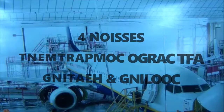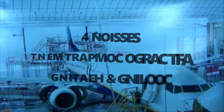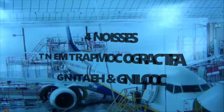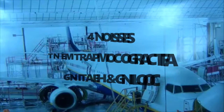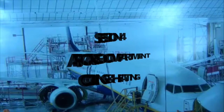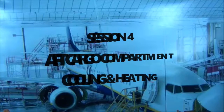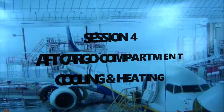You also have, of course, we talked about the trim air valve before, but we have the trim air valve that's located under the body fairing, and you can make sure you check with your MRO as far as different panels, because it could vary a little bit depending on some things. There could be a different configuration. Okay, so that's what you have. You have the temperature sensors. You have the selector, obviously, in the cockpit at 22 VU panel, and your valves.